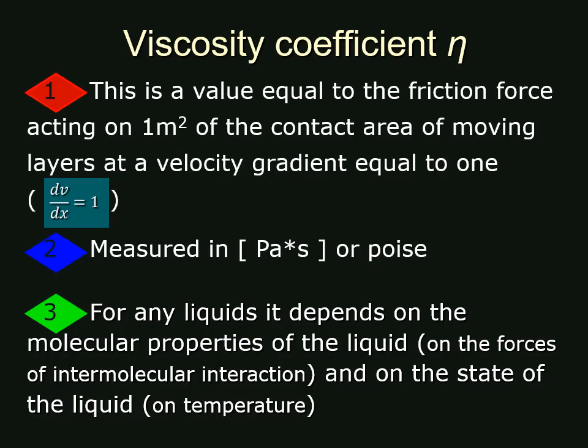First of all, it depends on the molecular properties of the liquid, that is, on these very forces of adhesion, the forces of intermolecular interaction. And secondly, on the state of the liquid. The state of the liquid is mainly influenced by temperature. Remember how the same substances, let's say oils, can behave when the temperature changes. At a temperature close to zero, it is practically a solid. When heated, it is less viscous, and at significant heat, it is already a very fluid liquid.